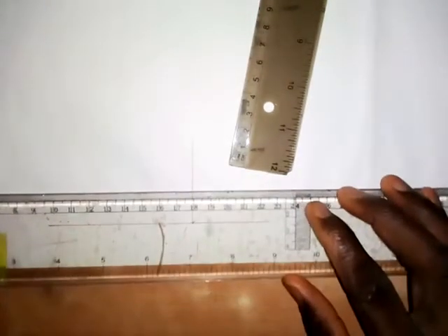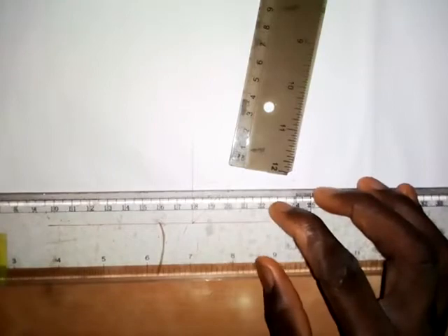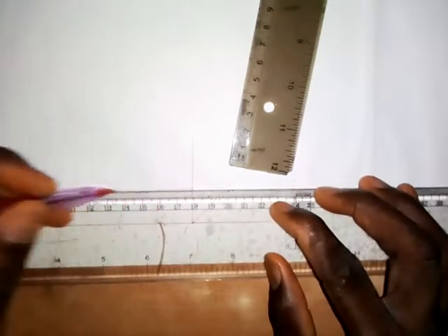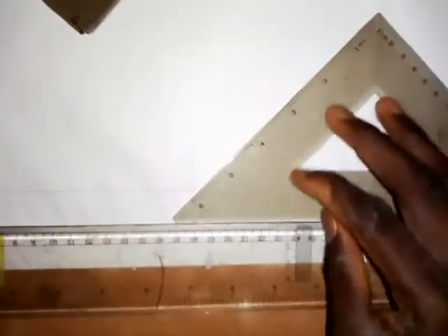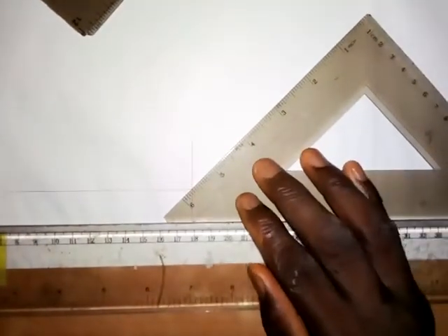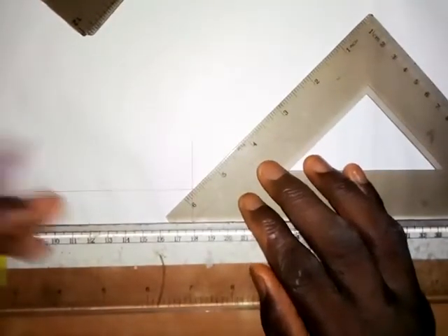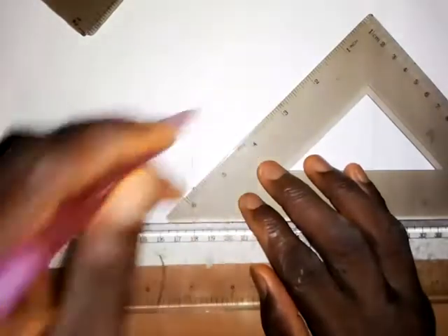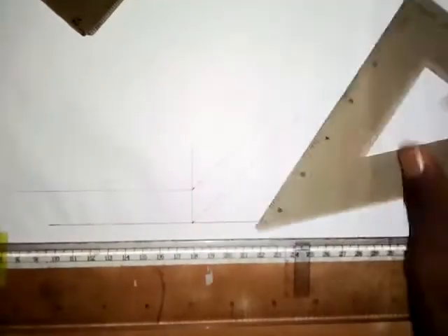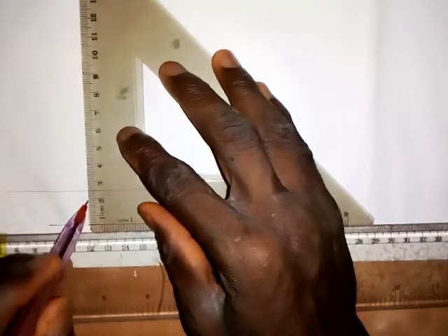this line that we have to draw here is parallel to this line. So you draw this one with your T square. You draw it to this side. Then you take your 45 degree set square and bring it to this point. So you draw this line. Then you come here and draw a vertical line, like this.